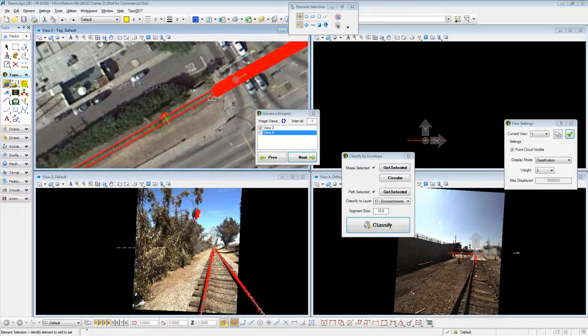Interesting about what you're saying about the vertical shaft. We've had a couple of jobs in London on the underground system where we've needed to prove the verticality of a shaft and whether the walls are inside or outside of a given tolerance. If you've got a path defined vertically, could the tool define where the construction is inside or outside of an envelope?